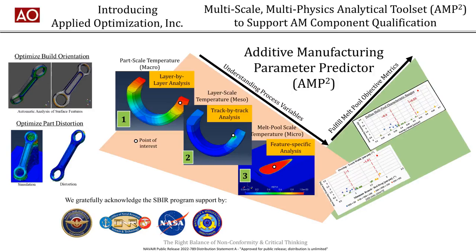We mitigate defects by attaining consistent melt pool formation, accounting for the non-uniformity of residual heat buildup, hotspots, and part geometry. We optimize most of the parameters allowable for commercial machines. This includes the usual laser power, scan velocity, line spacing, as well as special parameters such as the core offset, contour offset, multiple contours, etc. The parameter prediction uses automated algorithms so as to minimize the manual effort. The solution method is simple enough to be used by undergraduate interns. This is important because the simulations can be performed at a very low cost.